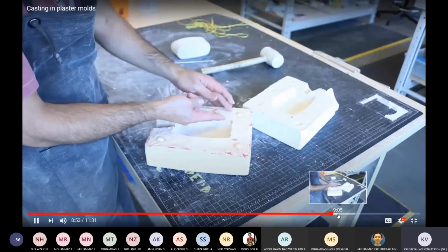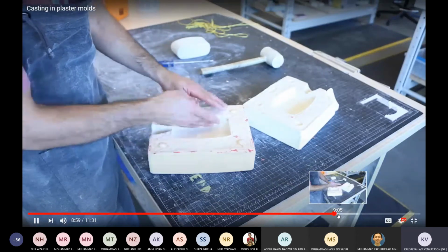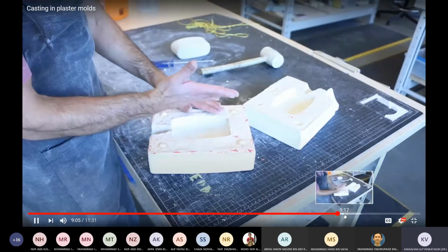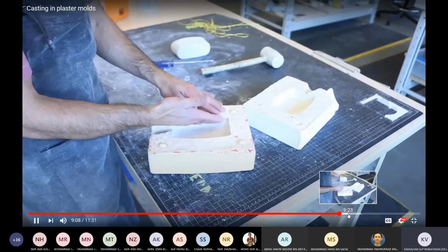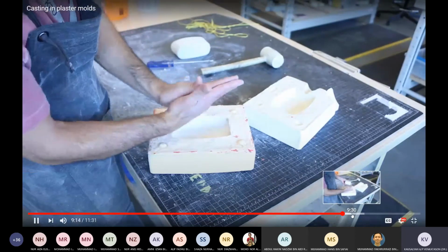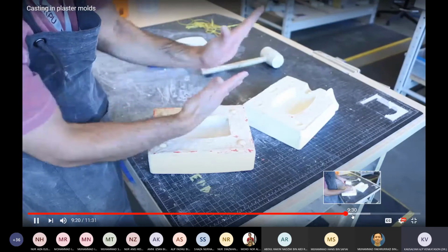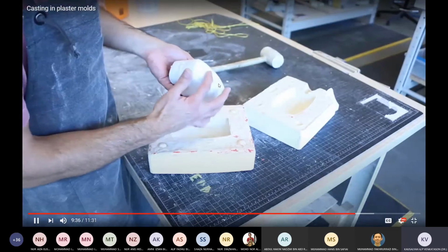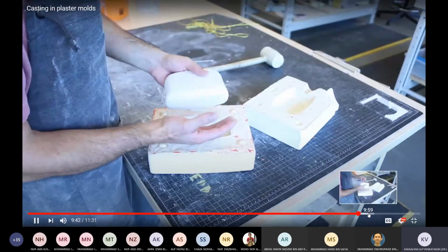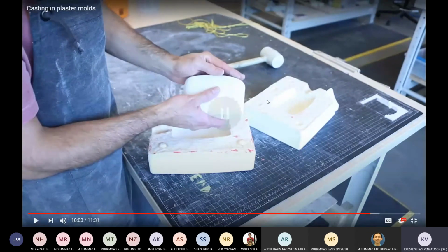But this is the interesting bit. When I was taking this out, it broke like this. What this type of broken piece means is that the mold had a negative angle. When I extracted the piece, the mold was on top of the piece, so when I extracted the mold, the mold broke. With this flat surface here, dividing this into two molds may not be the best idea. It may be better to divide it into three or four, or maybe more pieces, a different partition.